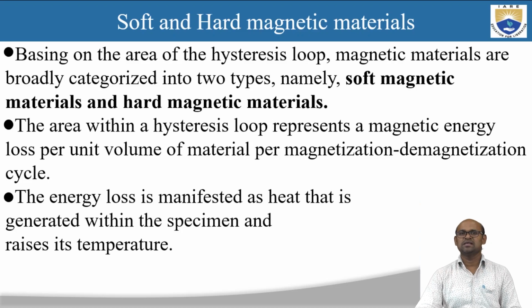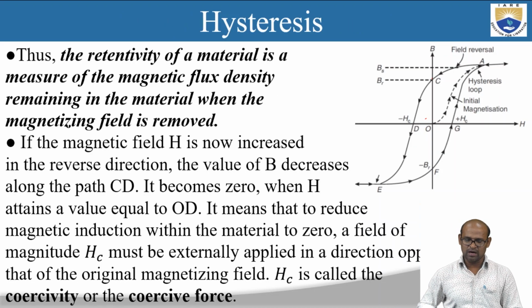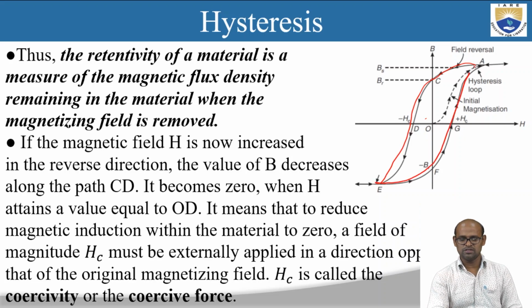So we can magnetize a material and make it a permanent magnet, and we can find there is some energy loss in a magnetic material as you apply a magnetic field. So the area under this BH curve will give us the energy loss of this ferromagnetic material under a magnetic field cycle.